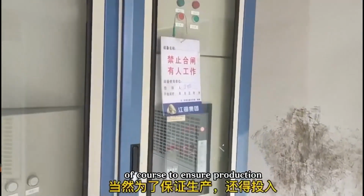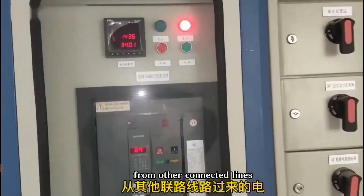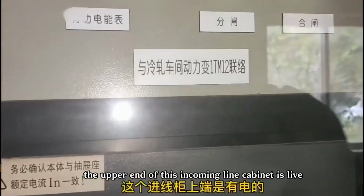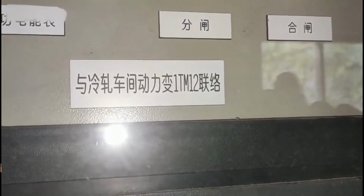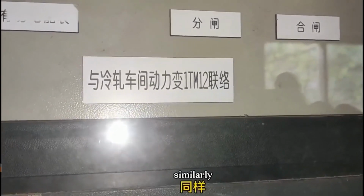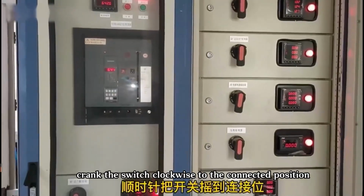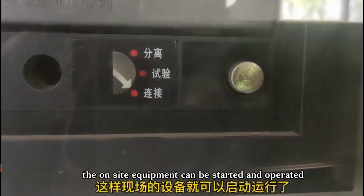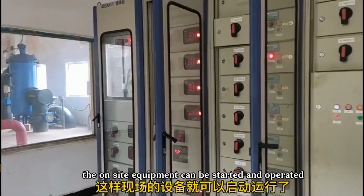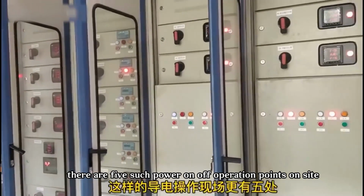Of course, to ensure production, we must switch to the power supply from other connected lines. The upper end of this incoming line cabinet is live. Now we can energize it. Similarly, crank the switch clockwise to the connected position, and then press the close button. This way, the on-site equipment can be started and operated. There are 5 such power on-off operation points on site.